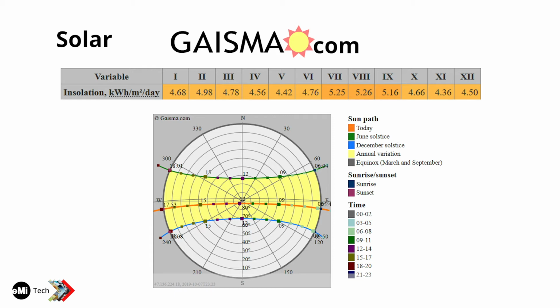So you basically take that angle, and then you look at, if you have multiple modules sitting like this, you're using some trig to make sure you're not shading the modules from each other during that period of time. So I'm not going to go through the trig right now, but I'm just giving you an overview so you're aware of that in your design.